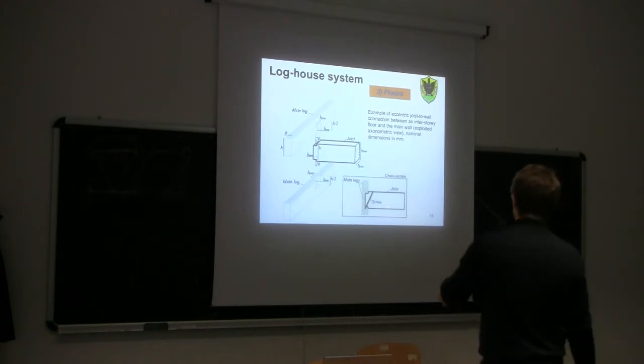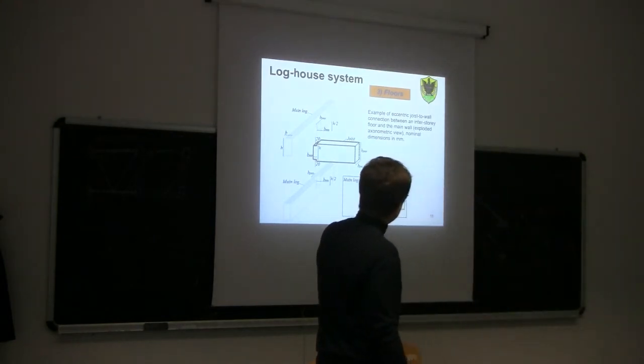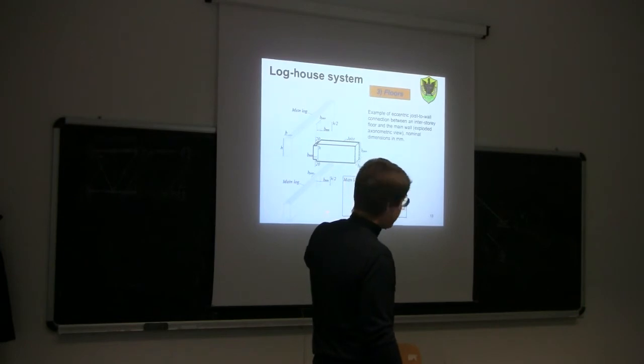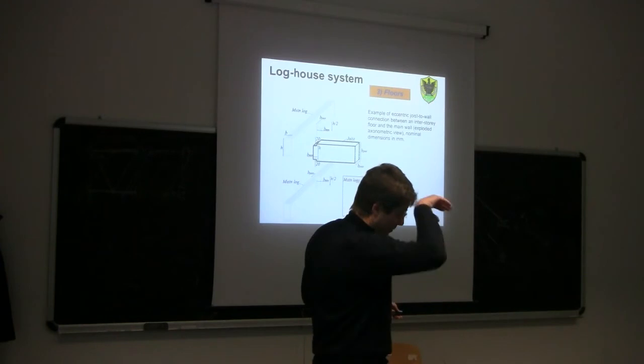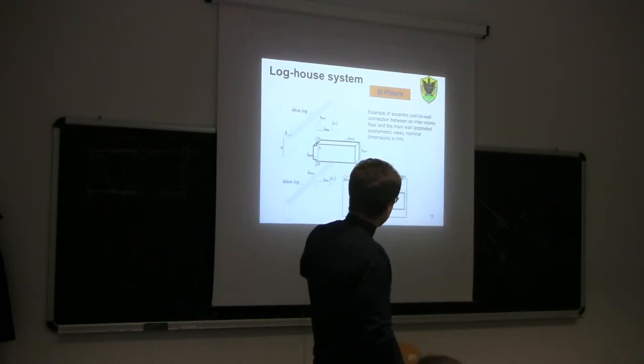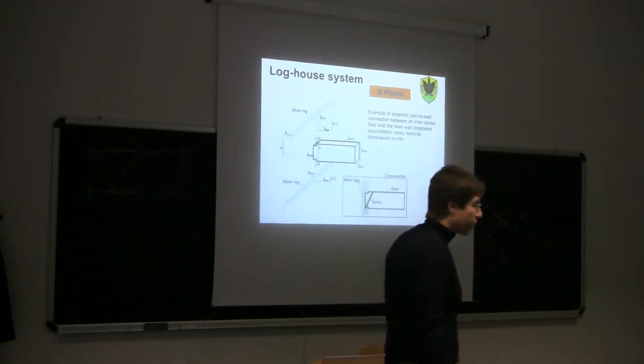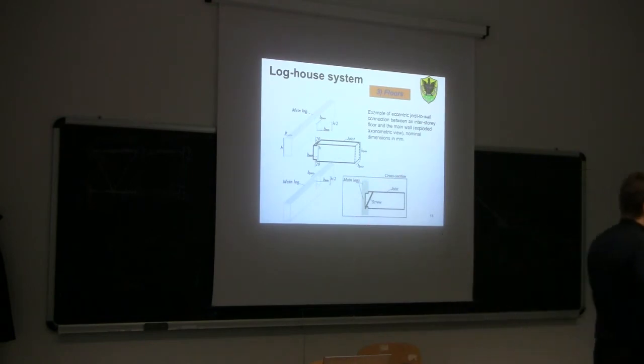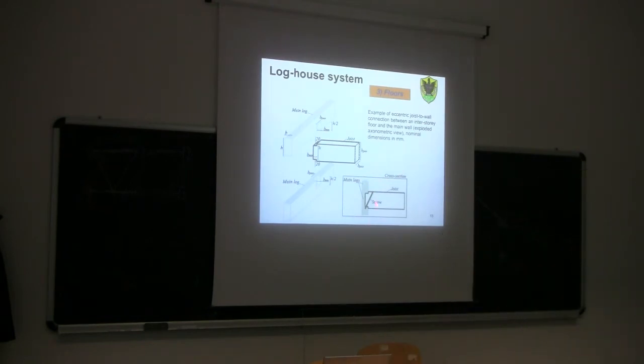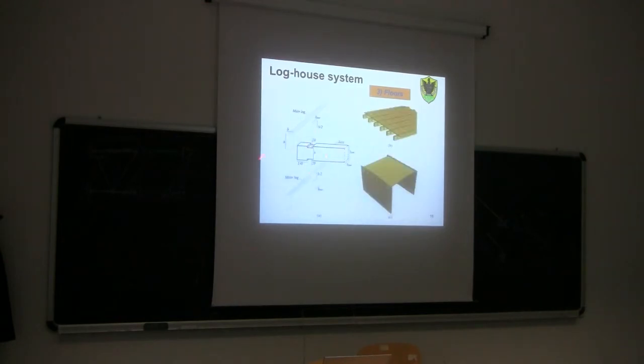So, for example, only here, if the joist doesn't go through, one screw is needed, because otherwise, in the case of displacement, for example in an earthquake, this part here may fall down. So in this case it's important to put the screw. Instead, if the joist can go through, like this solution here, no screw is needed because this is a restraint which can prevent the movement and the falling down of the joist.